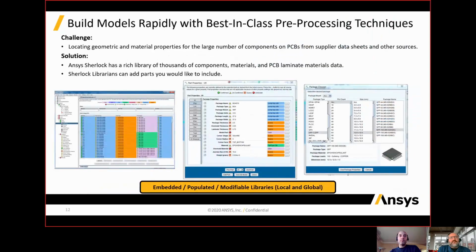Now, another key part here is when you're looking at electronic systems, there's often a lot of complexity, and the complexity arises from just the sheer amount of geometric features. We're looking not only at the number of surface mounted components, but also traces and vias, let alone if you have a housing that you're also including. So there's a lot of complexity geometrically. There's also a lot of complexity in terms of material behavior. Some components tend to be more linear elastic, but a lot of times there may be parts like solder that behave more like a viscoplastic solid. So there's a lot of different things we need to account for. And then, as we mentioned, there are a lot of physics conditions that we need to account for, things like drop test or thermal cycling, even static loading.